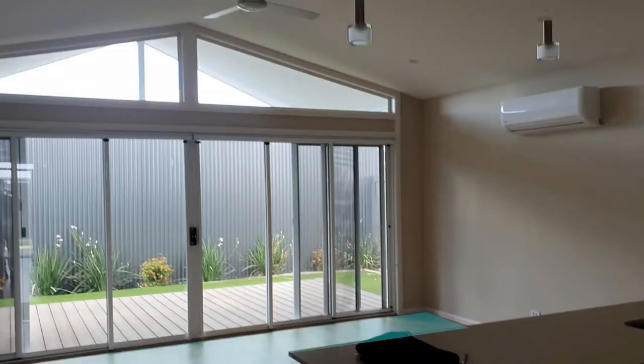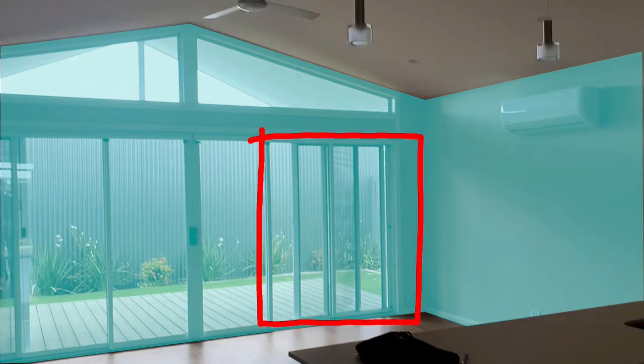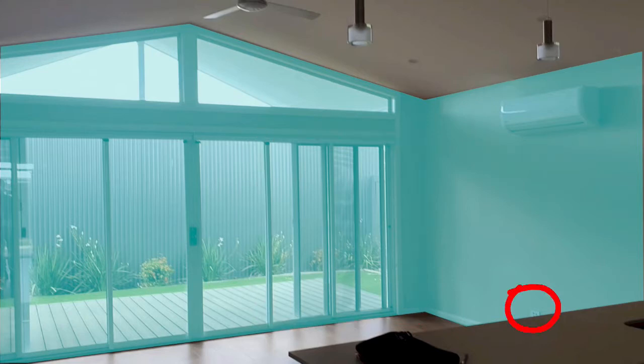A concrete slab is pretty safe, but a suspended timber floor is going to leak anywhere where there's a plumbing or electrical penetration through the floor or the bottom plates. Turn the house sideways and the water is going to leak through penetrations in places like behind the split system air conditioning unit, through windows and through electrical outlets.